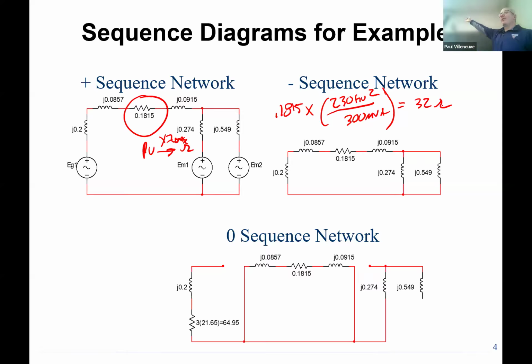But you can look at the per unit positive sequence diagram, and it's really pretty simple and basic, isn't it? It's just the generator and the motors converted to power sources, and then we include the internal equivalent impedances, all corrected to our new base. You can even tell that's J.2.